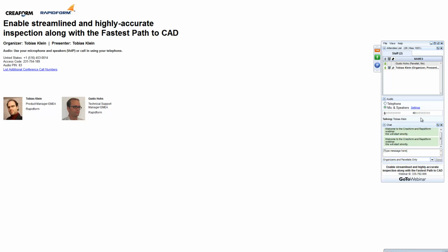Are all of these probings taken manually, or if I have a CNC run CMM, can they be taken automatically with that? Actually, we can virtually read any point cloud data format and inspect it against CAD, but the demonstrated method is designed for articulated arms or for tracked probes. So we cannot control a CNC or bridge portal CMM drive yet.